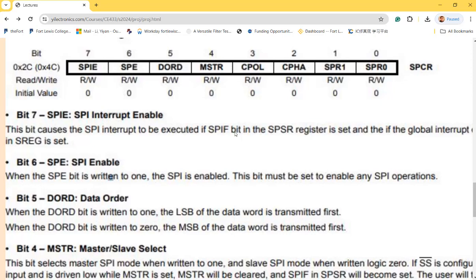So if you don't do anything with the clock polarity and clock phase for this register, what are they? Zero. So it's a falling edge. It's a falling edge taking in the data. As a falling edge, it's a 0 as an idle state for the clock. So in that case, if you don't configure these 2 bits, you have to make it right in your Verilog, right? So in your receiver mode,